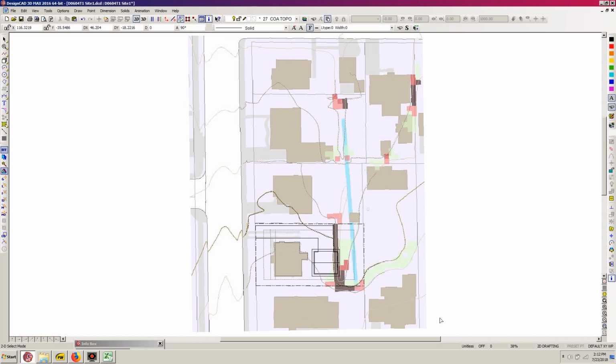We also know from our previous site plan, the one that we obtained from the Doe family, that our topographic intervals are at 2 feet. This site is basically dropping in elevation 2 feet for each topo line that we cross toward the north, so our slope is to the north.